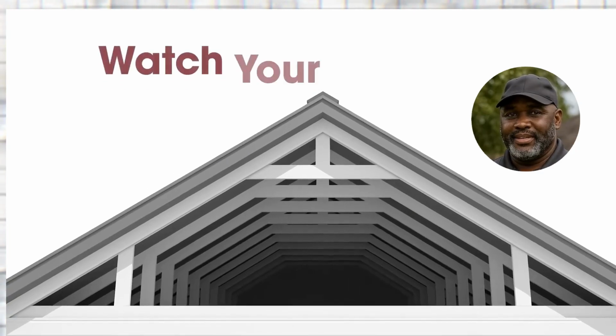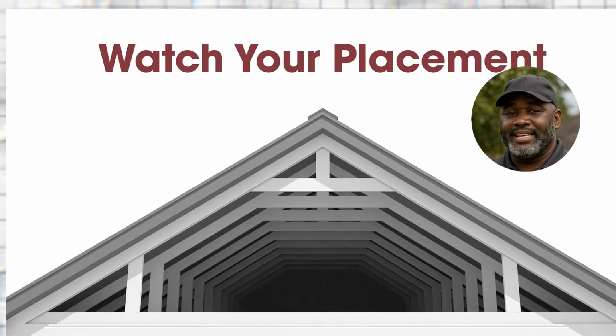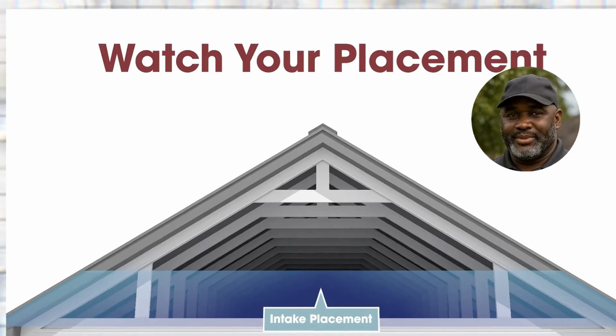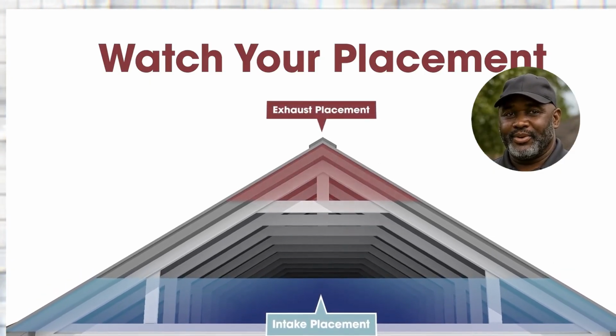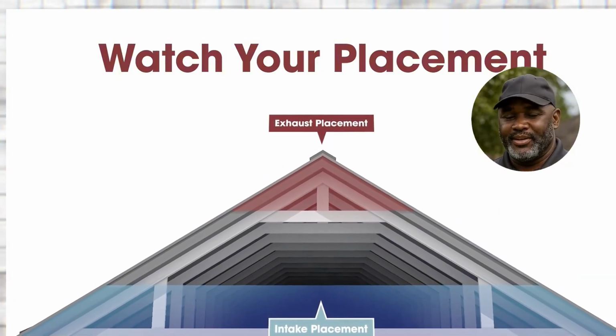The last principle is to watch your placement. For a system to function properly, intake needs to be located at the lowest part of the attic space. On the roof, this is typically at or near the soffit. Likewise, exhaust should be located at the highest part of the attic space, typically at or near the ridge of the roof.